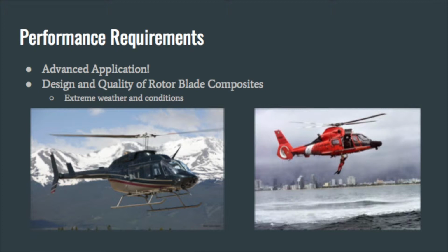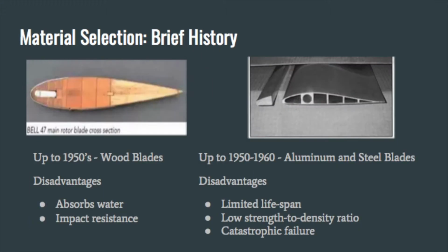Additionally, during rotation, the blades flap in the vertical direction, meaning materials with good flexural modulus characteristics must be considered. If the helicopter is used in marine rescue operation, it may also experience degradation due to salt from the ocean. For these reasons, only advanced forms of composites are selected in the design of helicopter blades.